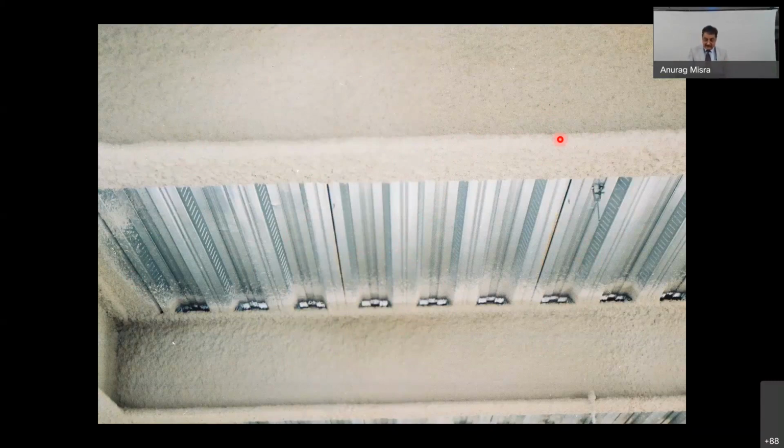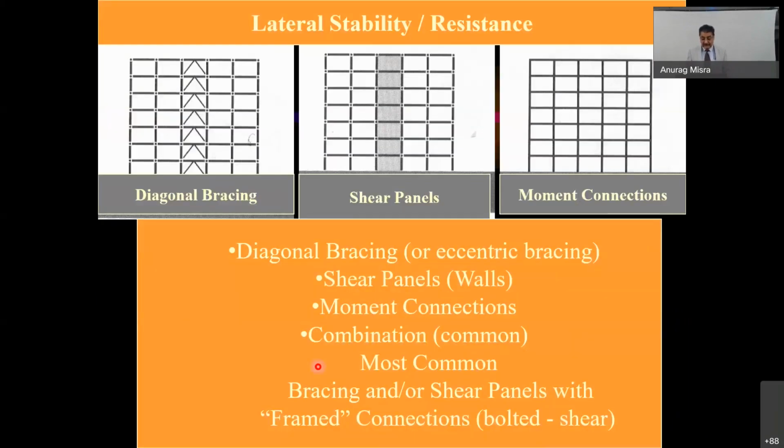So this is becoming very popular wherever you are going to use false ceiling, because in a steel building mostly you are using false ceiling in the structures. So you could actually do the shotcreting. It is very fast, and you can see that the whole steel beam is hidden inside the cement-based composite, which is able to provide good fire insulation, and that drawback is now not there.